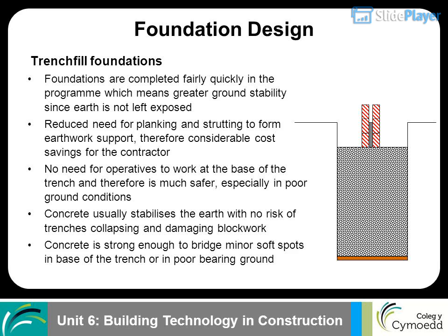Foundations are completed fairly quickly in the program, which means greater ground stability since earth is not left exposed. Reduced need for planking and strutting to form earthwork support, therefore considerable cost savings for the contractor. No need for operatives to work at the base of the trench and therefore it is much safer, especially in poor ground conditions. Concrete usually stabilizes the earth with no risk of trenches collapsing and damaging blockwork. Concrete is strong enough to bridge minor soft spots in the base of the trench or in poor bearing ground.